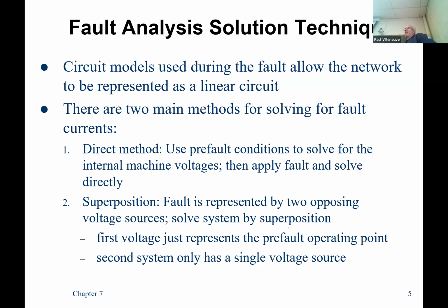Well, we're not going to use the direct method. Oh, yes, sir. But then if you can find the fault where there's higher current, let's say at generation, maybe there is higher current fault, then do it as if now. How do you know that the fault current's going to be at the generator? What if it's someplace else? You remember, this system is all networked.